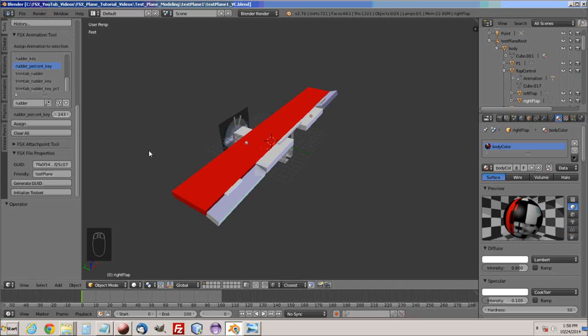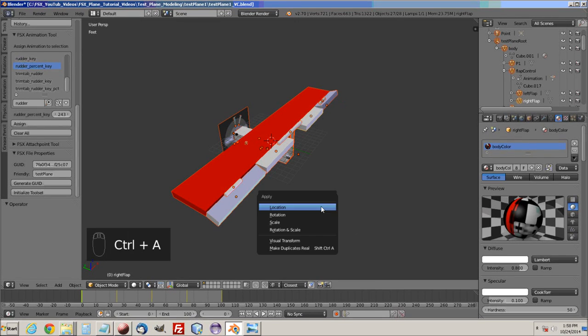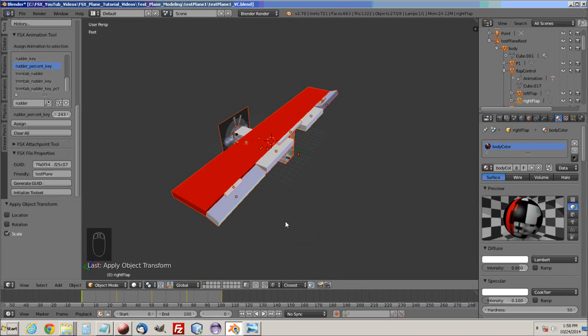As soon as we open our Blender, let's initialize our tool set. Just in case we've changed something and messed up the scale, let's hit the B key and box select our virtual cockpit model. Then hit Control A and click on scale to make scale back to default. Hit A to unselect everything.